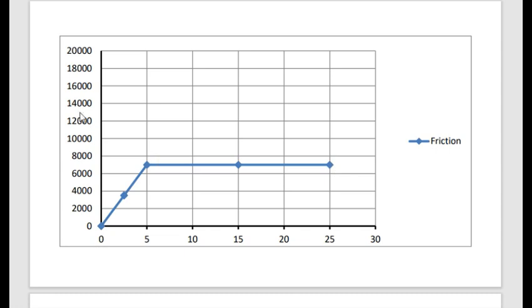This is the load, and this is the settlement that happened according to this load. Imagine that you have a pile that is pure friction, only friction. You don't have end bearing, as if you have a gap below the pile, so the pile is free to move down, but it is not free to move because of the frictional forces all around.